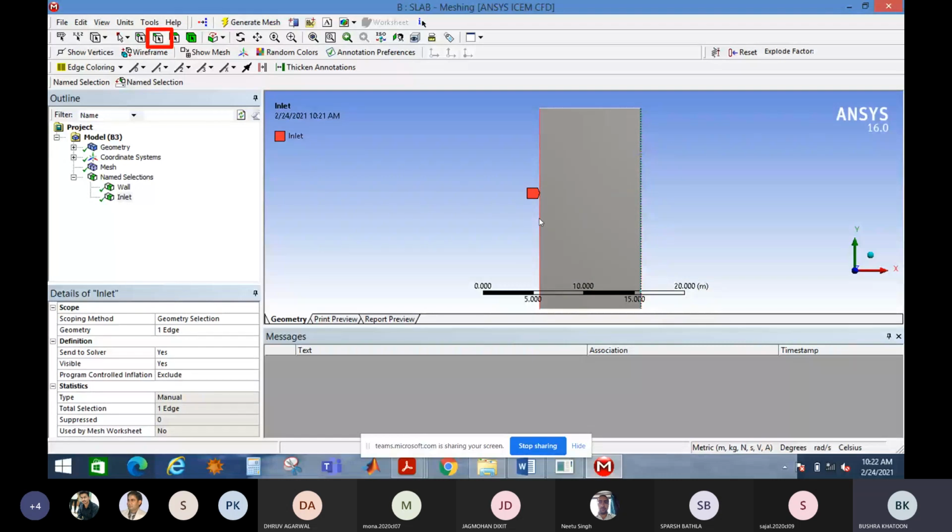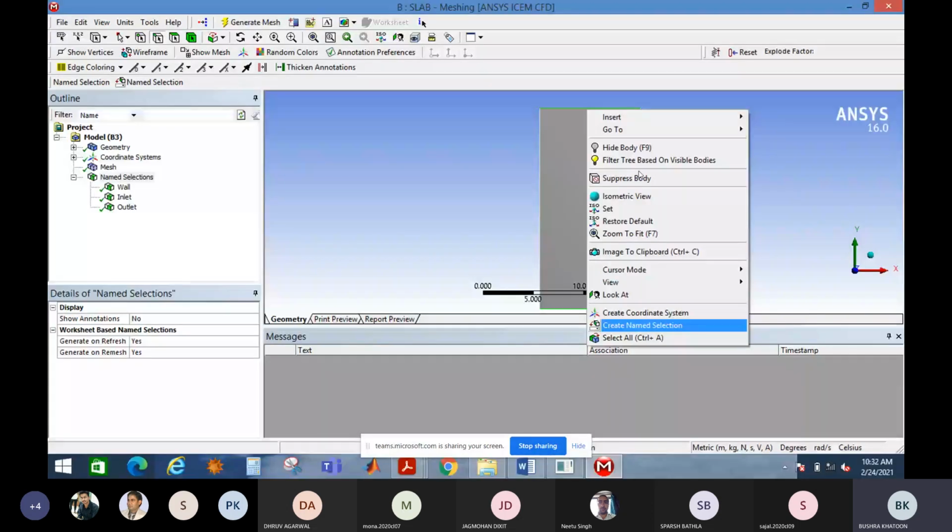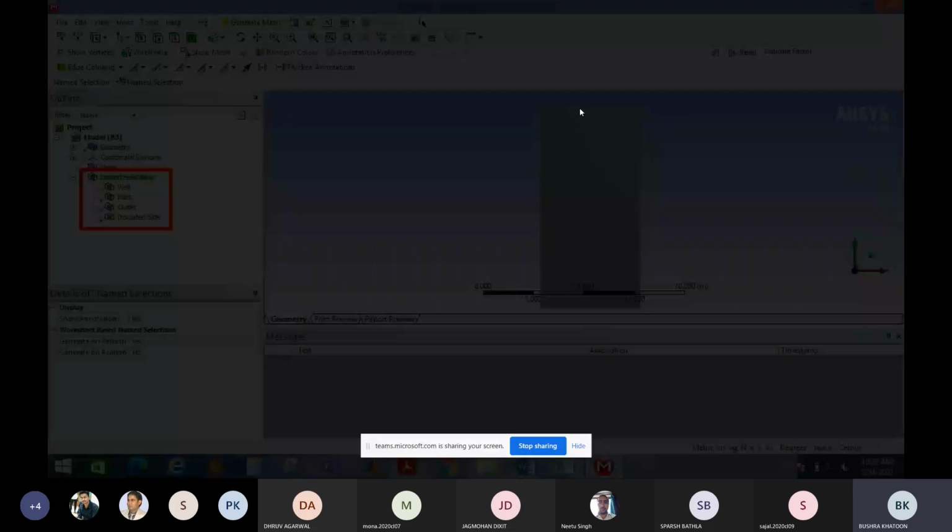But if you are dealing with a fluid flow problem, in that case you don't have to give the names left, right, top, and bottom. In the fluid case, you have to give names based on where the fluid is entering, from this side or this side or this side. So, like, consider the fluid is entering from this side. So we have selected this surface and give the name inlet one, and these two surfaces are considered solid surfaces, and this is your outlet.